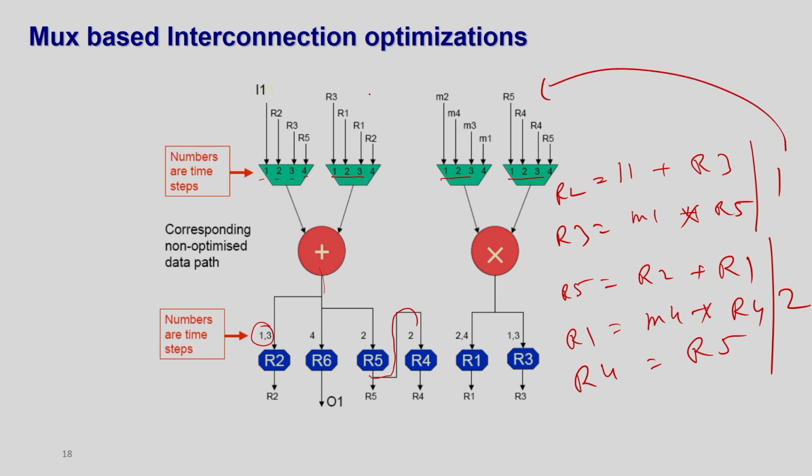and based on this schedule behavior I actually identify these mux connections. So, you will tell me that you need a 2-bit control signal here, a 2-bit control signal here, a 2-bit control signal here. So, my question here is, can I optimize this circuit further? Okay. To do so, let us understand what we can do here, because this looks very fixed, right.